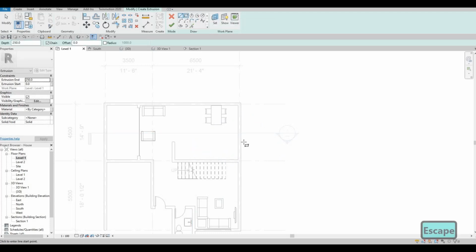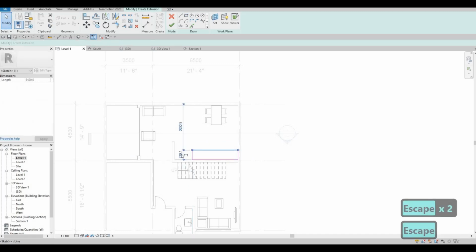So click on rectangle and let's create an extrusion like so. I'm just leaving some space for the fridge. Here it's around 800. This one I'm gonna put 700, because this is the base of the cabinet.